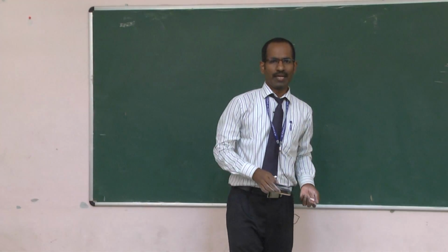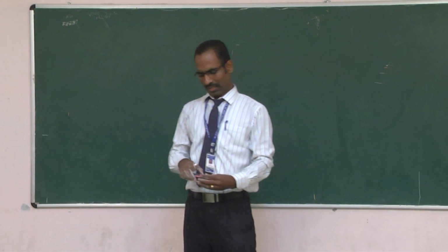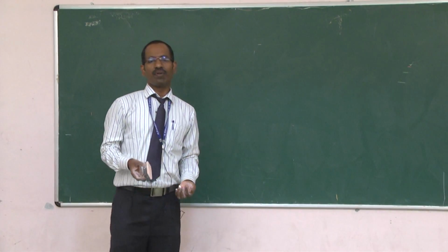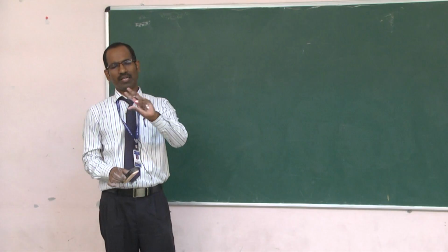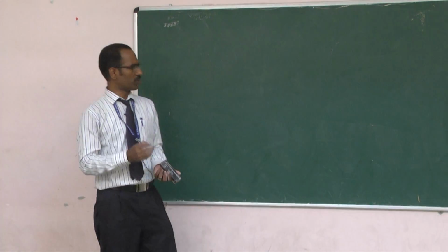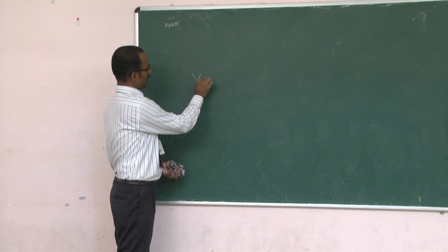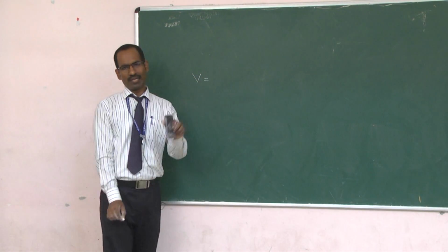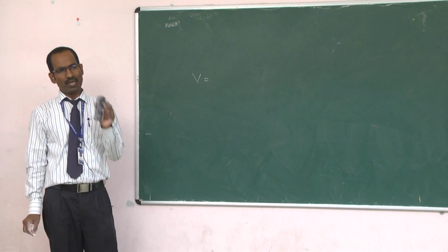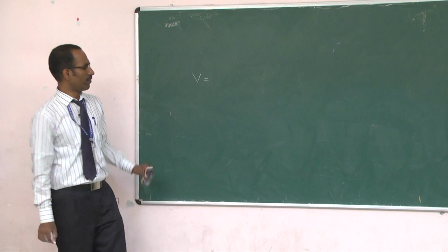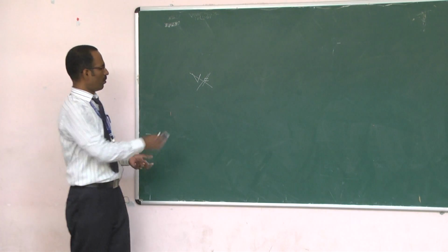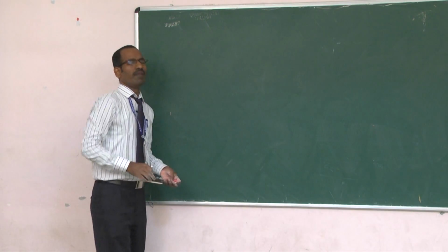So from this we can conclude that an alternator is a generator which generates electrical power. The electrical power generated from the alternator must always be maintained within the tolerance limit. Specifically, we are concentrating only on the voltage. The voltage must be within the tolerable limit. If there is any change in the terminal voltage of the alternator, it definitely affects the appliances connected in the circuit. Not only the performance of the appliances, it will affect their lifetime also. So we must maintain the terminal voltage of the alternator within the tolerable limit.